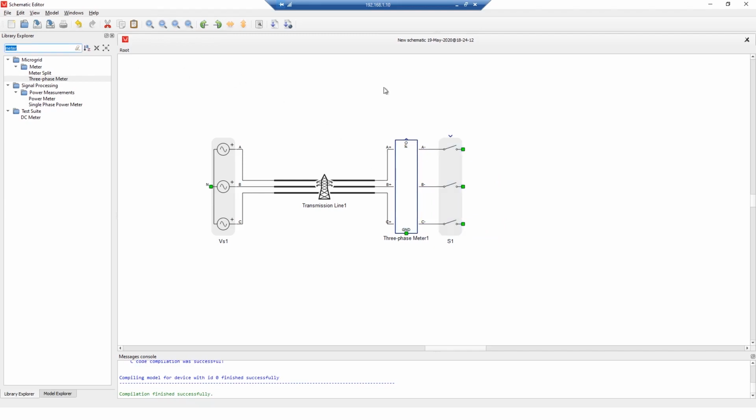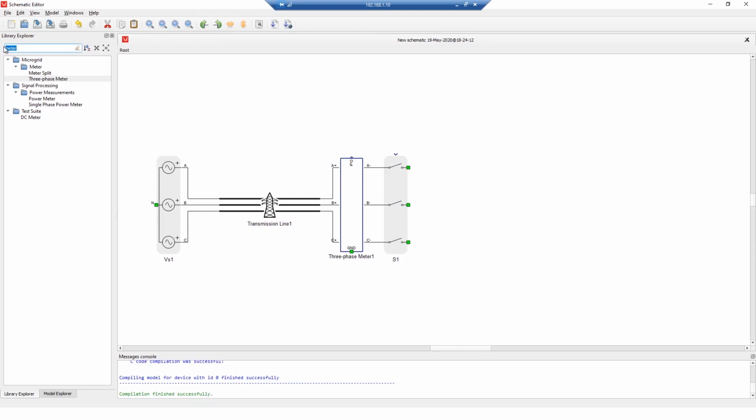and then what I want to do now would be to actually map the digital inputs. So inputs to the simulation mean outputs from the relay, so I want to map those here. These will be close. This will be open. And I'm going to use a set-reset flip-flop like this. So close is set, open is reset, like that.